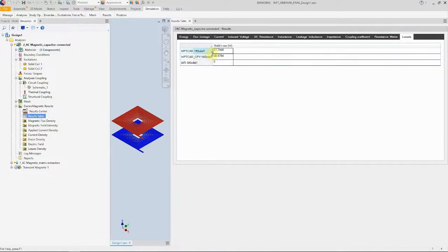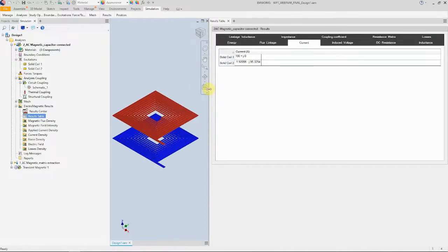In the first coil and second coil, we almost have 30 watt copper loss, and it is almost negligible in comparison with the power that can be delivered in 100 amperes that is connected to 1 ohm resistance. The transferred power due to this current and the resistance load is almost 10 kilowatts. That is a nominal power for many types of wireless power chargers for EV.